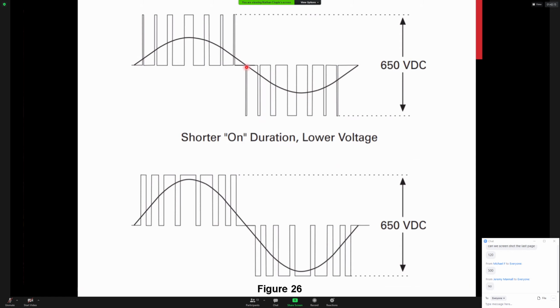The controller, in order to determine if this is supposed to be a 60 hertz waveform, all of this switching takes place in what you should all know is the time it takes for one alternation at 60 hertz, which is 8.3 milliseconds. So 8.3 milliseconds this way, another 8.3 milliseconds this way, and that brings us to our negative alternation.